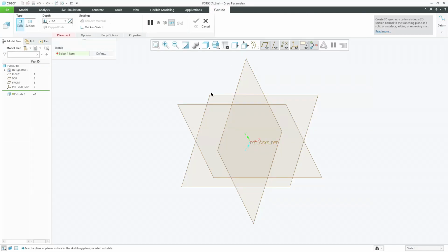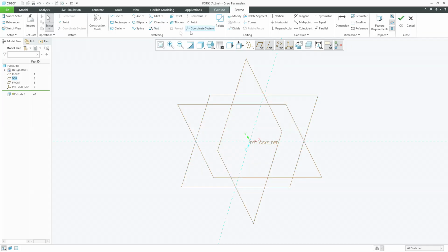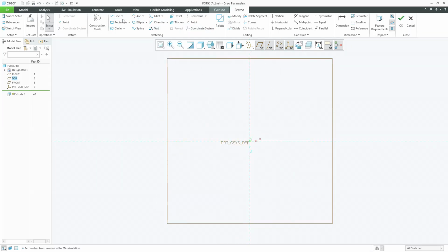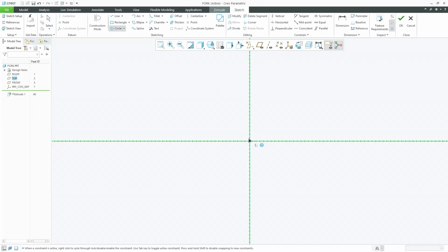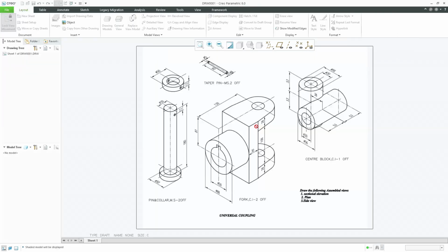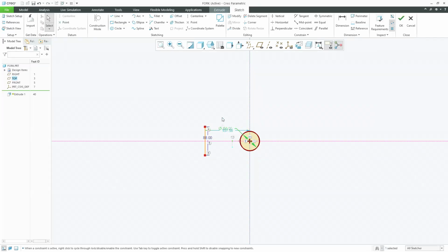So for that I'm selecting the extrude command, selecting the top plane, and I'll click sketch view. Before creating a circle I would like to have center lines here, and I'll disable all these planes, center lines, axis lines, everything. Next I'm going to create a circle. The diameter is 88 mm, and I'm going to draw a straight line which is symmetric on the horizontal axis, and this would also be 88. So I'm going to modify this as 60 and this will be 88.